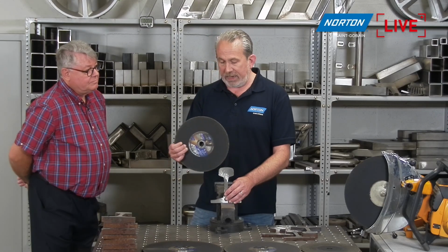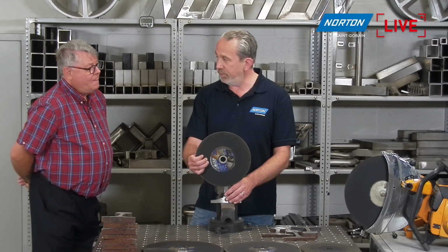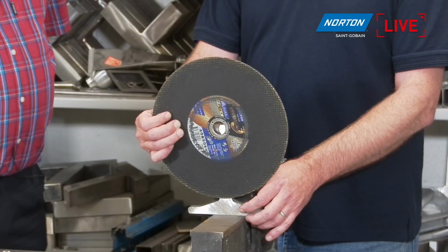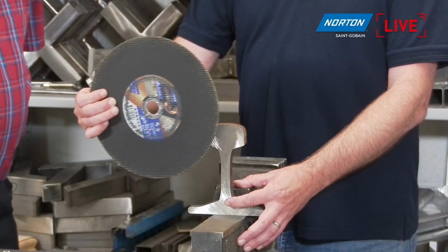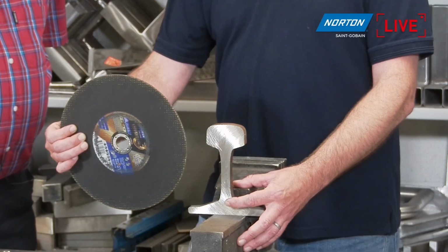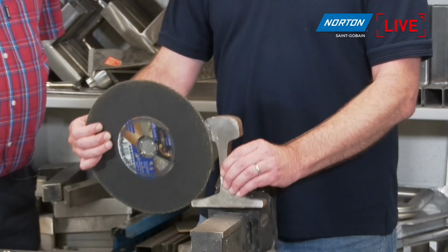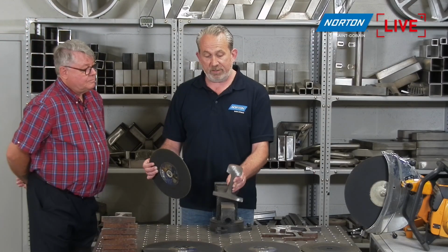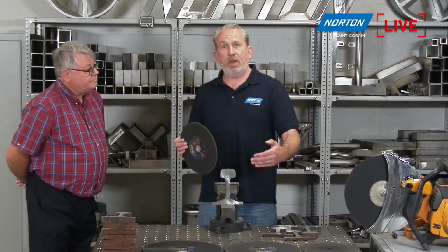Once you've cut through the head, you've gone all the way through, you then get to the top of the web, and we continue to oscillate backwards and forwards in this part a little bit as well. Then when you hit the top of the foot, you bring the blade out to the outside of the foot and cut through the foot. What we want is a blade big enough in diameter to go through the whole of the foot and cut off in one action. That's the ideal. So we get one cut without taking the saw from the opposite side.